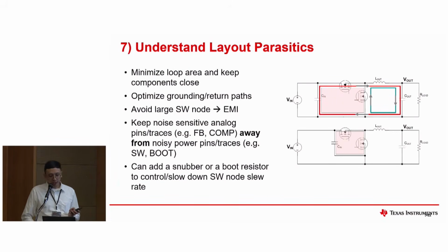So of course, in terms of the layout, you should definitely understand the layout parasitics, as you guys mentioned. Definitely you have to consider minimizing the loop areas and keep the components as close as possible, for both the input side and also the output side, the switch node side. This is an example of optimizing your layout. In terms of the schematic, if you can bring everything much closer to each other, the input caps to the switch node, that would be much better. This can definitely avoid large switch node ringing, which can result in EMI.